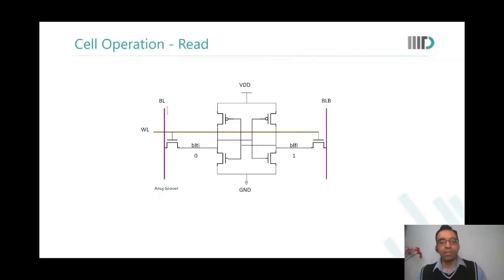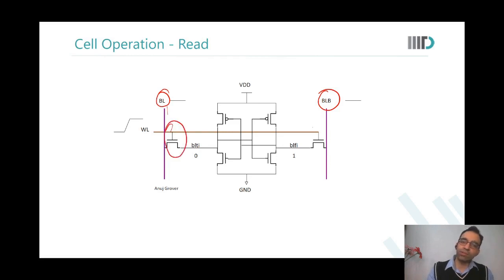Okay, great. So now how do you read and write into this latch? To be able to read from this latch, what you do is you first pre-charge the bit lines. So these are bit line and bit line bar. You pre-charge them and you take word line to be high. When this particular set of NMOSs are turned on because word line went high, what happens? They start to connect bit lines and the internal nodes. This side stores a 0 and this side you pre-charge to VDD.